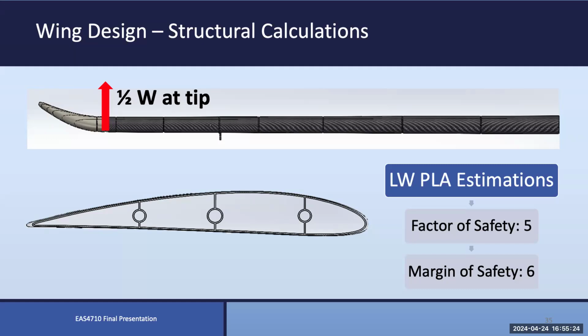You know, again, I realize that wasn't actually the right load case to consider, but if you're applying a big factor of safety and then finding a big margin of safety on top of that, that should be an optimization flag, right? Or a flag to consider a more realistic load case. So, yeah, let's see. Okay.